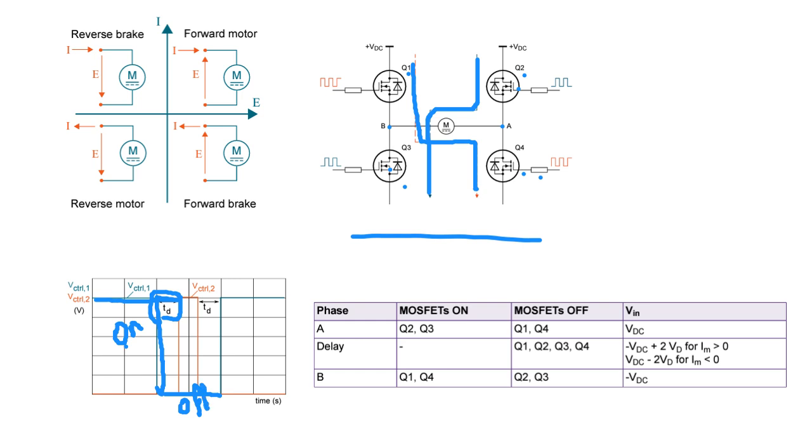Duty cycle here is a 50 percent ratio. It means that if you have, for example, 24 volts and apply a 50 percent duty cycle, it means 12 volts on your screen. Actually, you can create a square wave signal to the gate of the MOSFET, and then you will regulate the speed of your motor.